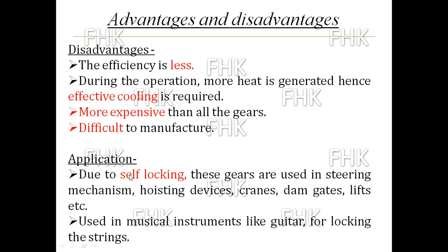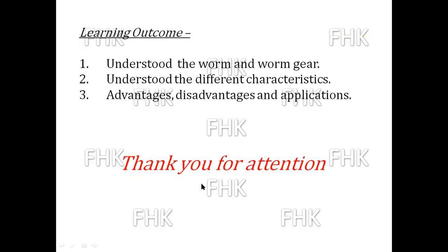The application is due to self-locking. These gears are used in steering mechanisms, hoisting devices, cranes, dam gates, lifts, etc. At the same time, these gears are used in musical instruments like the guitar for self-locking of the strings. So this introduction part may be asked in the examination for 4 marks: give the advantages, disadvantages and applications of worm and worm gear drive.